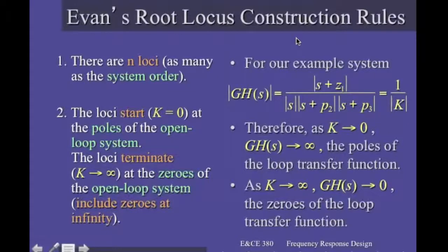So in this example, in which we have an order 3 system, look, the denominator is a polynomial of the 3rd degree in S. We will have 3 loci, 3 trajectories, which represent the loci of the closed loop poles when k is raised from 0 up to plus infinity.